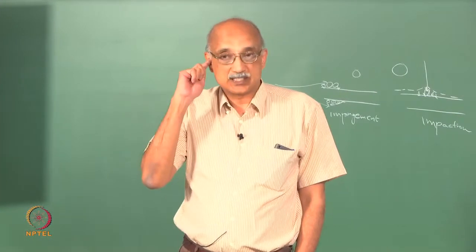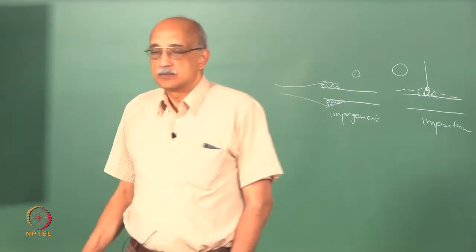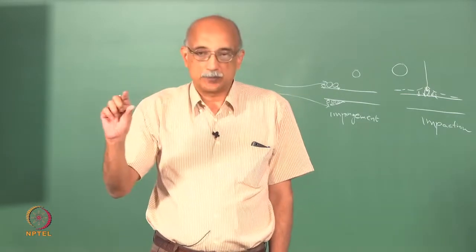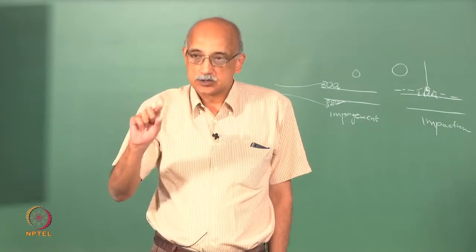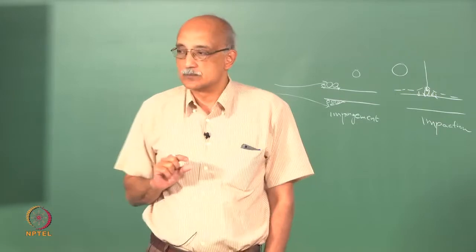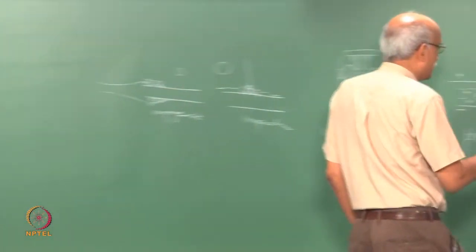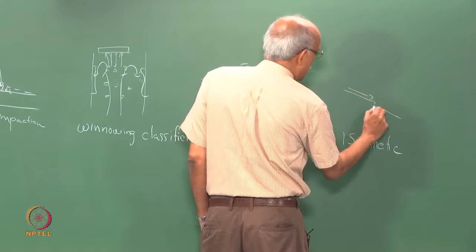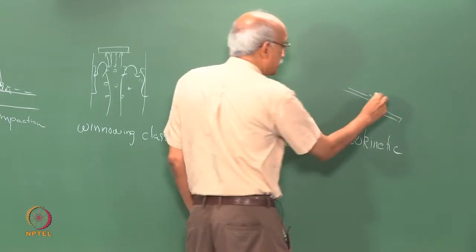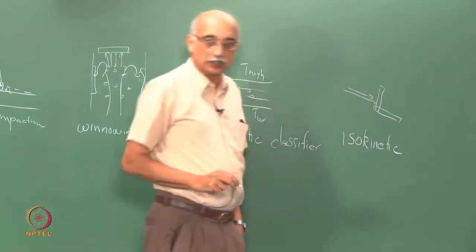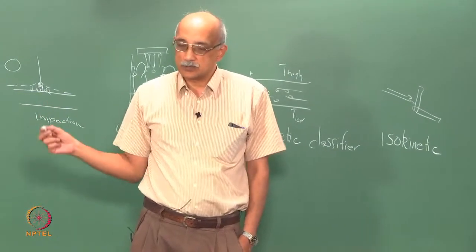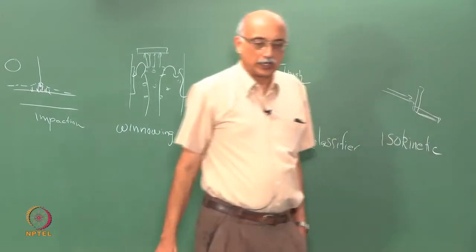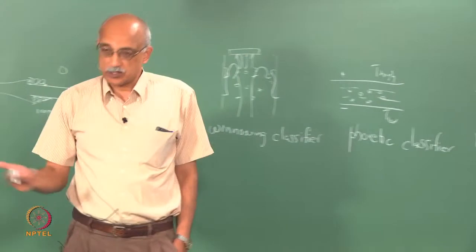So, the first thing you would do is characterize the airflow in this room, right, and then you will set up your collection equipment in such a way that it aligns to the airflow at that specific location. So, if the airflow in a particular area is in this direction, then your collection device must also, either if you are trying to capture large particles, it must be perpendicular to that direction, or if you are trying to collect by impingement mechanisms, it should be parallel to that airflow, or if you are trying to set up a filtration apparatus.